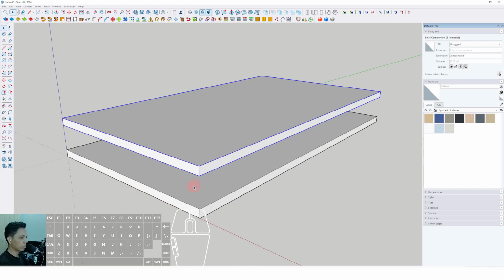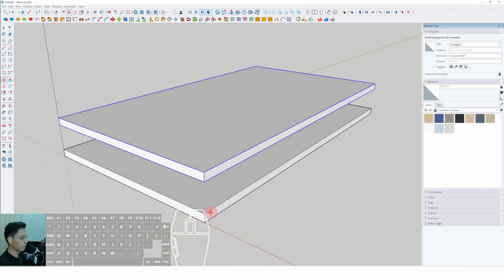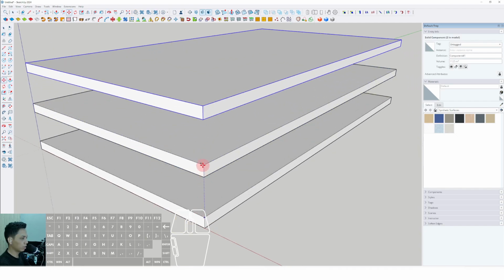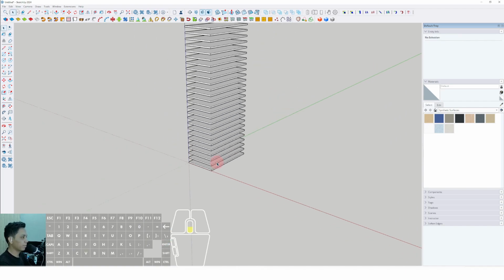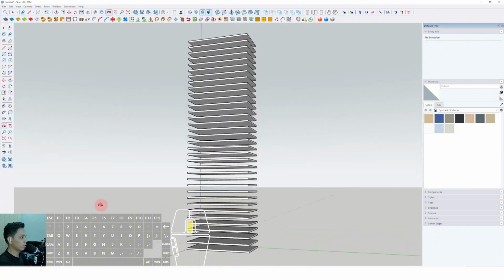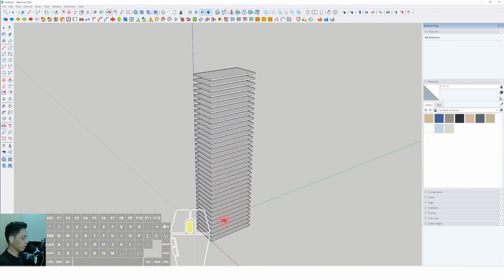Okay, well, now we move again from this point until this point, then type x30 or x33, enter. This is the result of the basic high-rise building.